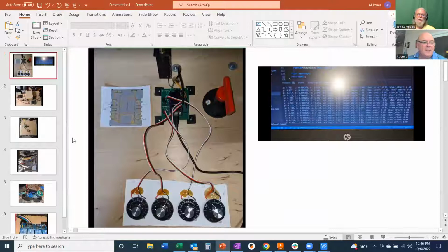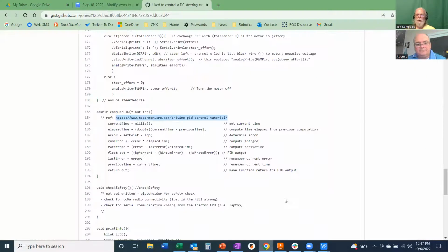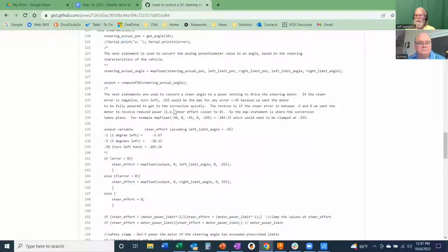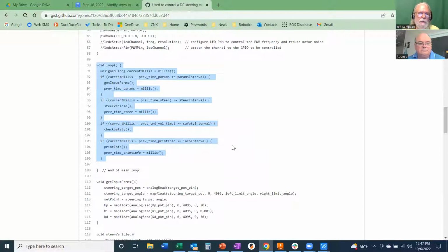Okay. So another thing I noticed is your timers. You had one timer that says run the motor at 20 milliseconds, another that says print out the values, and another about reading your pots. Remember, this is just a configuration tool. I realize that, but I think when I point this out, you're going to go, oh, of course.